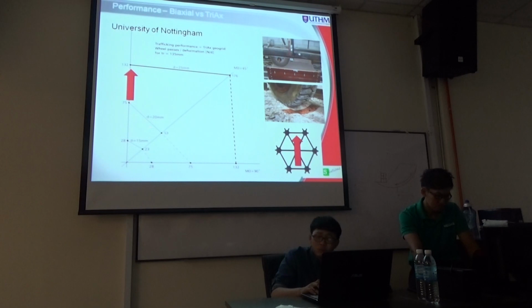The same test was run on this multi-directional geogrid. In the machine direction, after 132 passes we achieve 25 mm deformation. At 45 degrees to the machine direction of the geogrid, after 176 passes we achieve 25 mm.